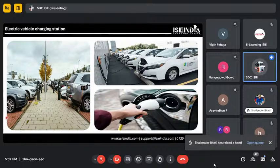Along with that, when we are talking about BLDC motors and permanent magnet synchronous motors, you will find that Hall effect sensors are there. Along with that, in these controllers, the throttle is also one of the sensors, where we are getting analog signals from the Hall effect sensors. As per that only, we enhance the speed of the motor or the speed of the vehicle, right?